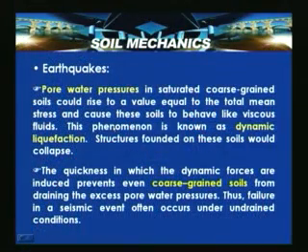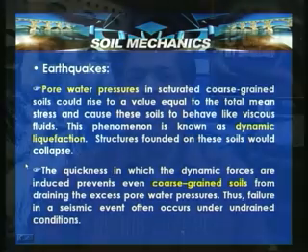Simply put, if there is a building resting on a slope, and initially, before the dynamic shear forces act, it is stable, it will turn unstable because of the dynamic liquefaction phenomenon. The quickness with which the dynamic forces are induced prevents even coarse grained soils from draining the excess pore water pressure. Thus, the failure in a seismic event often occurs under undrained conditions. So, because of the short duration, even for coarse grained soils, it is very difficult to dissipate the pore water pressure.